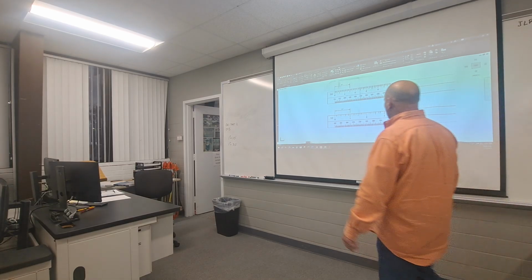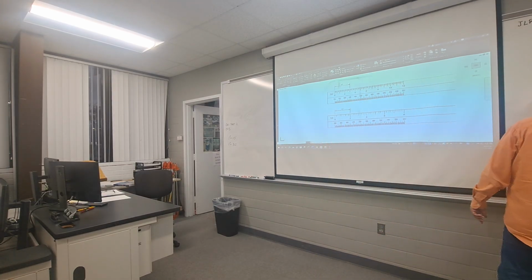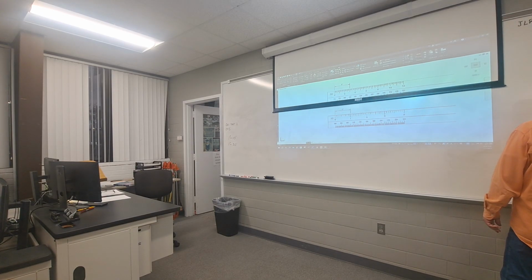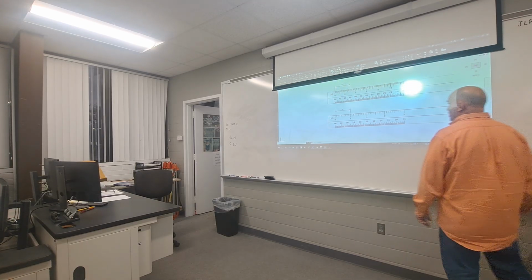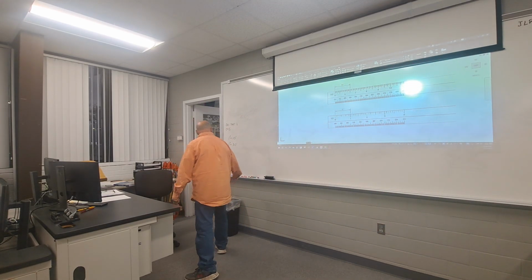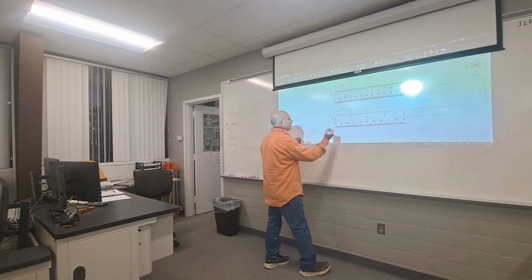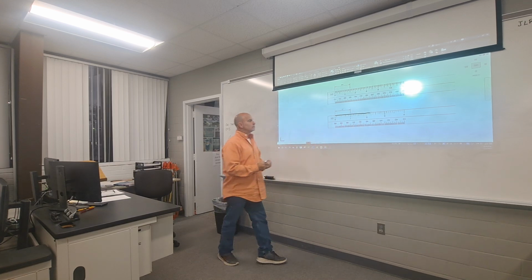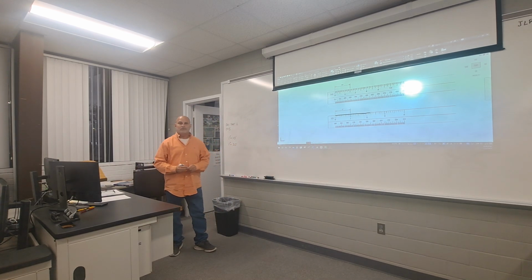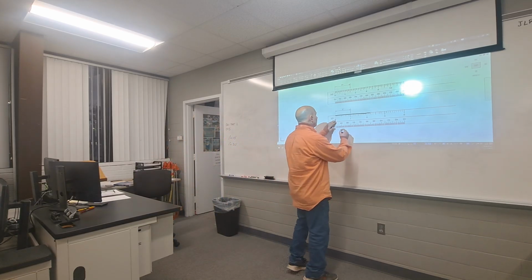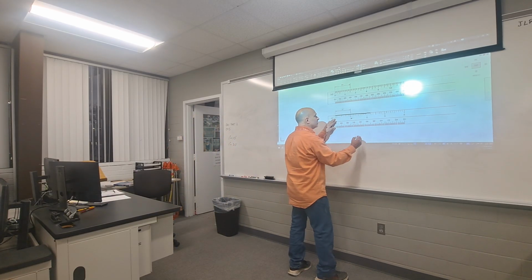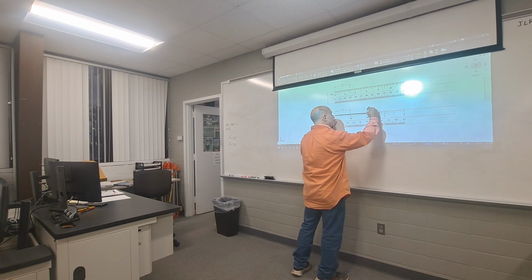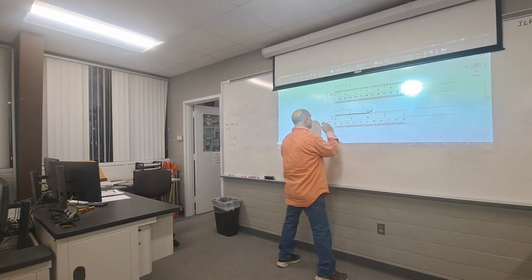That's okay. The way you measure with your engineer scale, you put one end of the line on 0, and you see where the other end falls. So if I were to randomly put a line on there and measure it, put one end of that line on 0, and I see where the other end falls. So I look at this and I say, okay, there's 0 feet. I have one end lined up. That really is 10 feet. That really is 20 feet. Mr. P said each one of these lines were 1 foot. That would be 21, 22 feet. There's my answer.